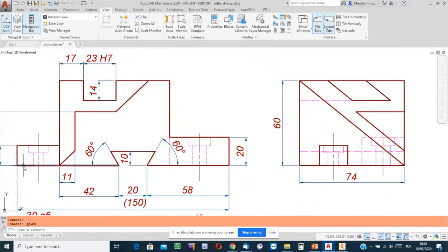After the manufacturing stage, when the object is manufactured, if someone measures the distance from here to there, he or she may find the value not 20, less than 20 or greater than 20. But the important thing is that if the measured value is in the range bounded by the upper and lower limits that have been assigned for this feature, then we can say that this part of the object has been manufactured sufficiently correct in size. We cannot say exactly 20.